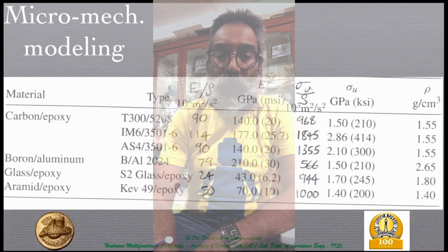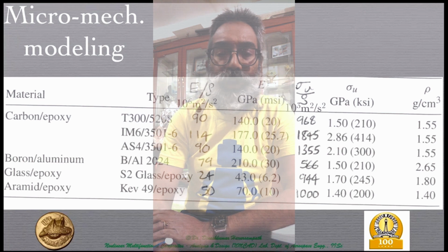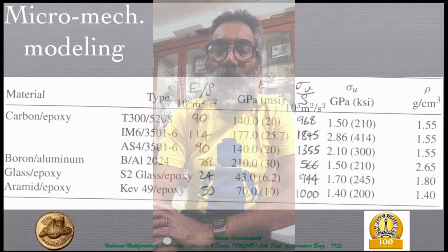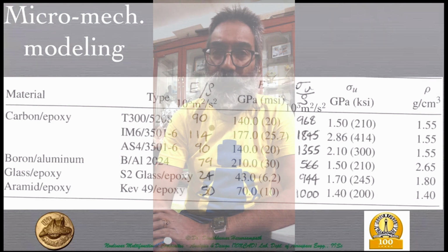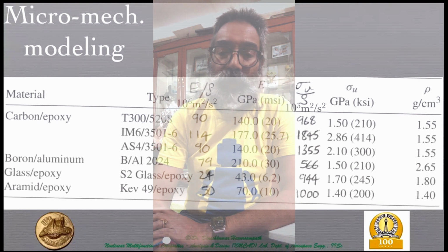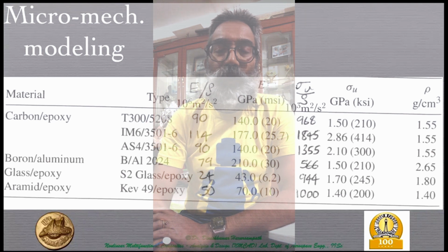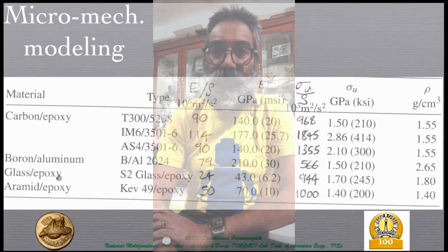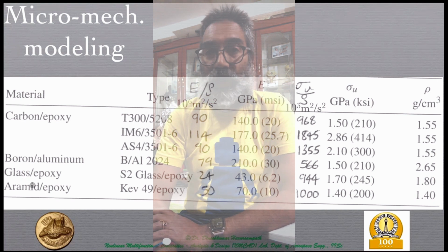So now, here the specific epoxy is not mentioned, but nonetheless these would not change way too much because they are dictated primarily by the fiber properties along with the volume fraction of the fiber, which we assume is in the range of 0.4 to 0.6, 40 to 60% of fibers. So now you see that S-glass is kind of comparable with the metallic performance as far as a stiffness-based design is concerned. So if deformations are the most critical, you might as well go for a metallic alloy if that is a cheaper option or more readily available option, rather than even glass epoxy for that matter.